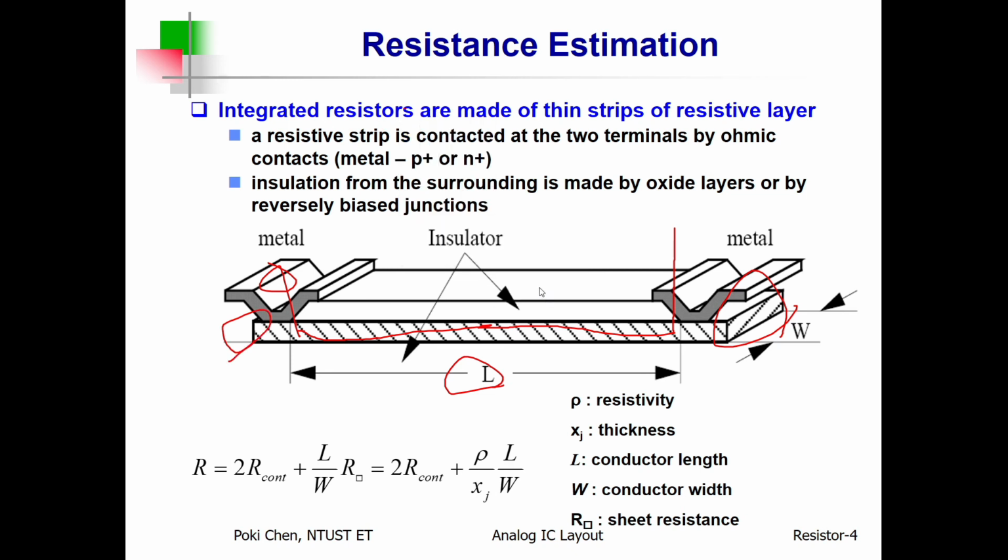What is the impact for such kind of no attention? No attention means what? You don't need to have any kind of dummy layout here, over there, to prevent any kind of over action of the boundary. No, forget about it. Never mind, this portion is longer or shorter. It doesn't have any kind of impact on length, right? On effective length. So who cares? I don't. How about you? Neither, right? So forget about the dummy layout to the both ends.